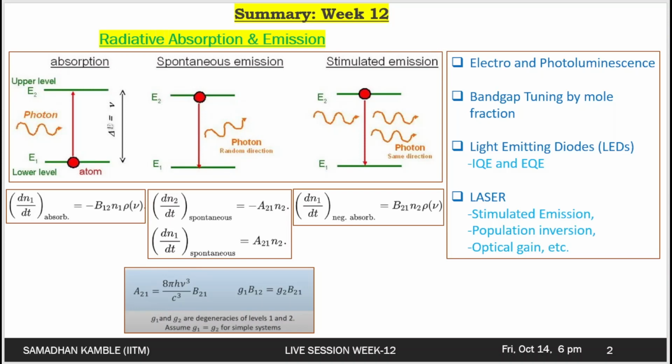And if the energy is more than the band gap energy, a photon can be absorbed as it interacts with the valence electrons and elevates the electron into the conduction band. The probability of this interaction, that is absorption, is higher when the incident energy is way larger than the band gap energy. This interaction creates an electron in the conduction band and a hole in the valence band, which is nothing but our electron hole pair. So this is about the absorption process.